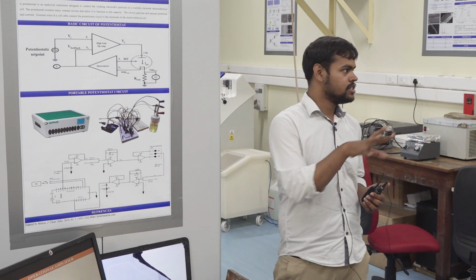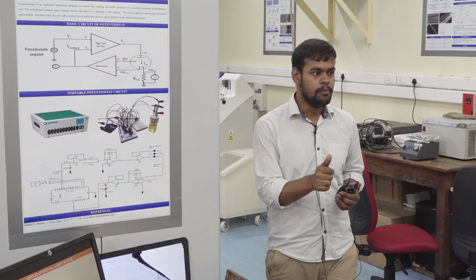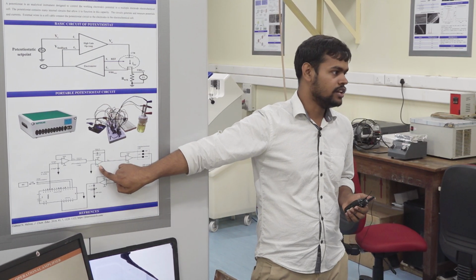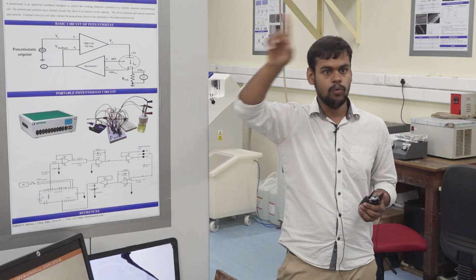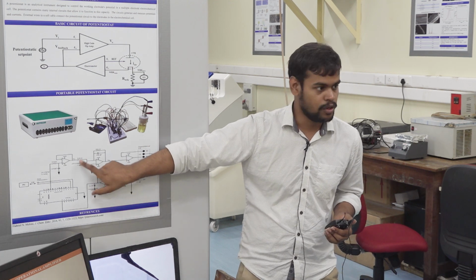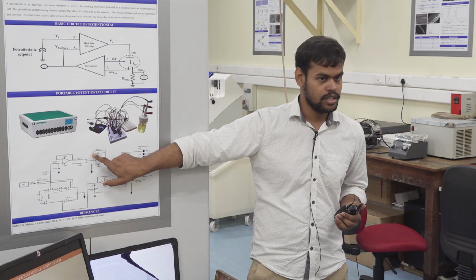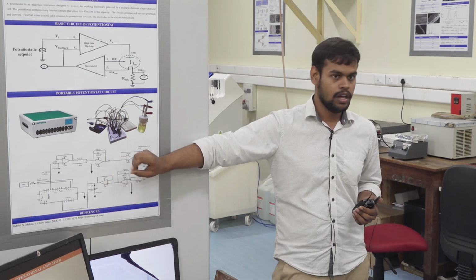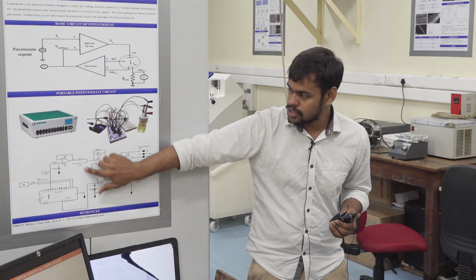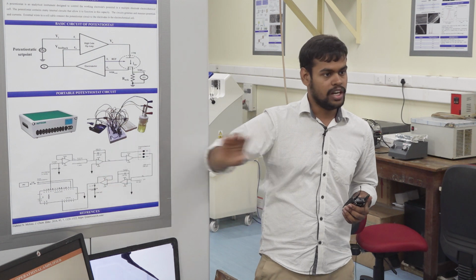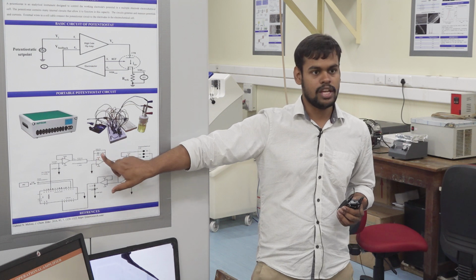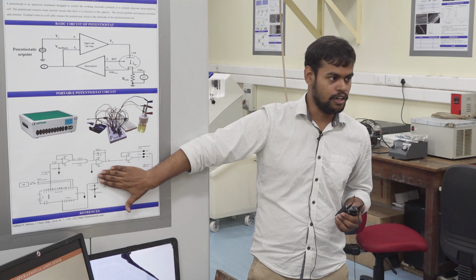Now, when we say operational amplifier, it's a high impedance thing. When I say high impedance, it means it will never allow a current inside it. So whatever the current is, it has to go to the outer loop of the circuit, or it will not go anywhere. So current coming from these 2 points will enter this, and it will move through the 200 ohm resistor. Now, you will ask why I use the 100 nanofarad capacitor. This is also a kind of RC filter only. But while I am doing the calculation, I am removing the 100 nanofarad part because I am using it for stability purposes of this circuit.